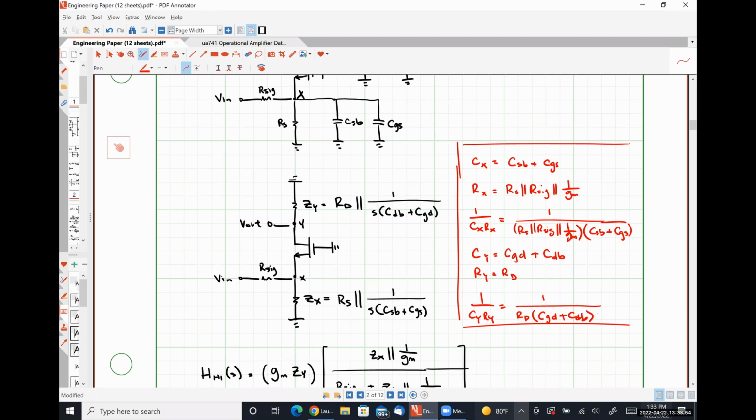So it's very similar to what we did. I hate to tie things back to things we did in earlier classes, but that's how my brain works. When we were doing parallel and series RLC circuits and trying to figure out the equivalent resistance seen by the energy storage element, we take out the energy storage element, so we open circuit them and look in with our input signals shorted out. That's exactly what we did. And then from the perspective of the resistance, we look in and see what our equivalent energy storage element is, which is what this is.